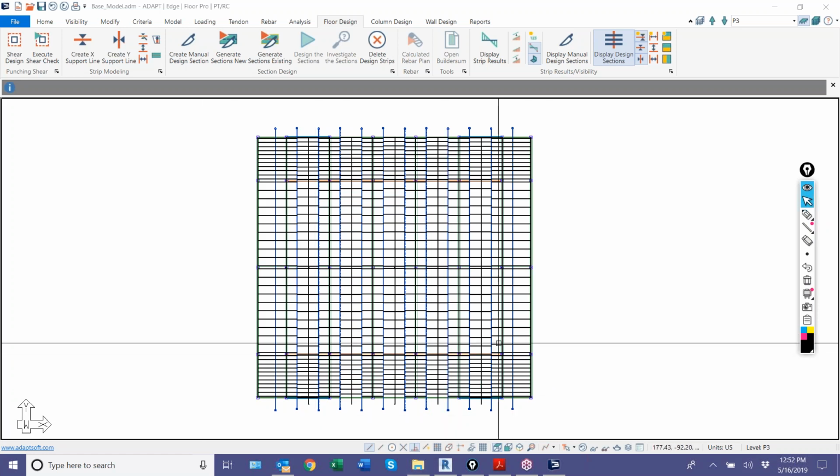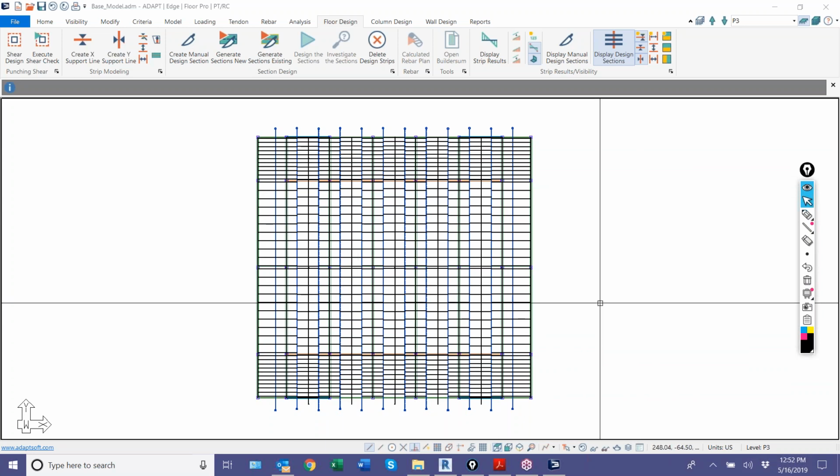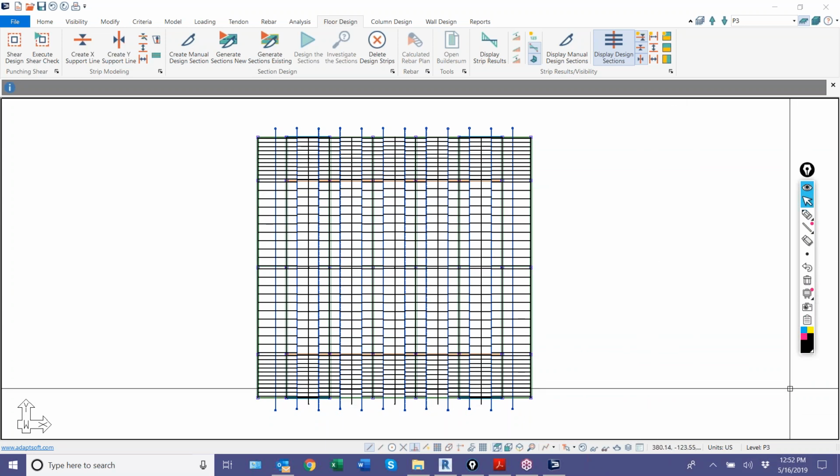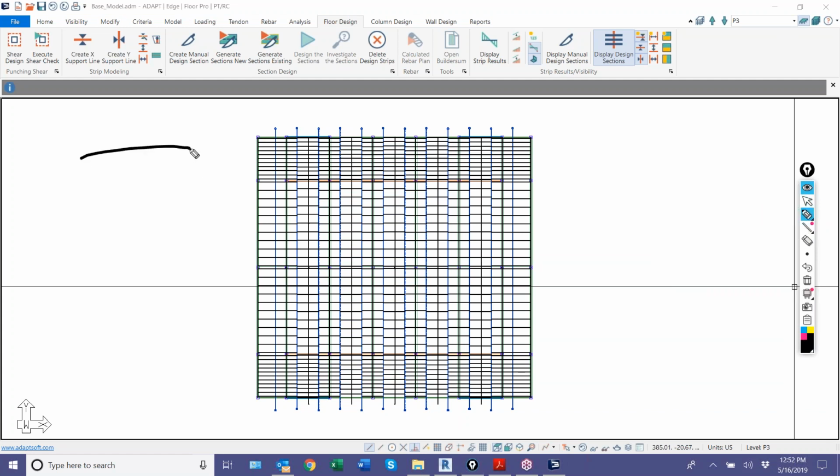The reason for that is in order to create the flange on the bottom. If I let's say I have a slab. This is at reference plane, let's say 3, and then we have a stem. And then in order to create this element for the bottom flange, let's say the bottom flange needs to look like this. This would have to be a shell element.